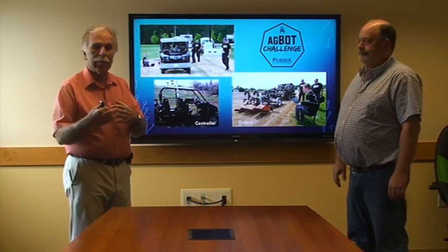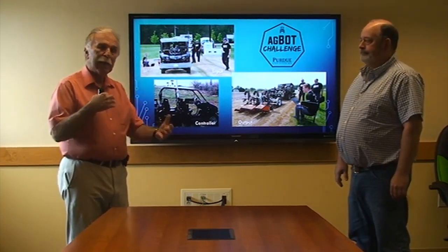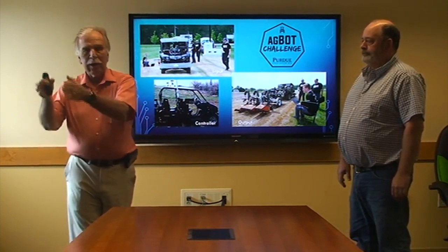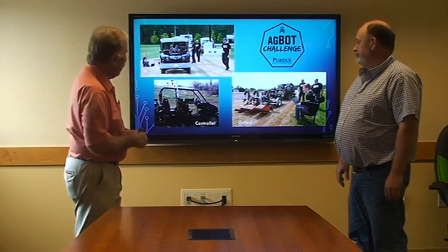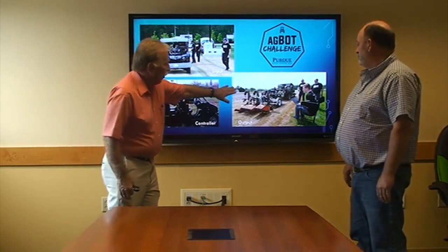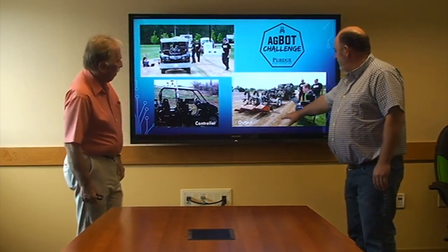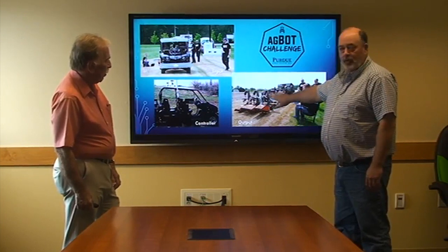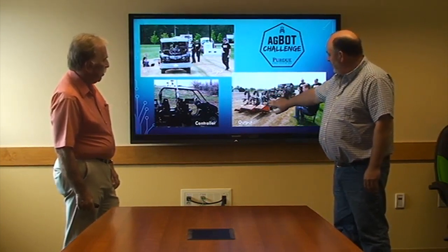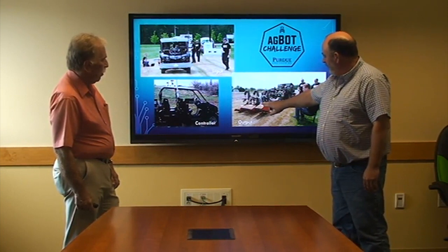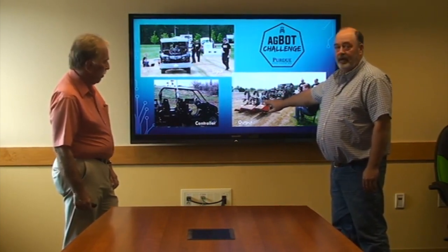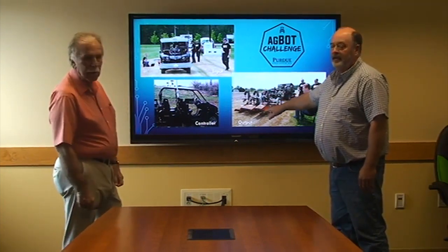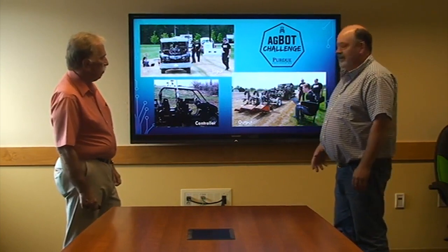So the camera that identifies the weed indicates the location of the weed, whether it is in the row or between the rows, etc. And then it feeds that back to our output device, which is basically a rototiller, these three orange things, and it has linear actuators that basically raise it up and down. And then within the row, we have some solenoids, which are basically on/off. That's another output device. We turn on and off this flow of liquid to spray on top of the crop, depending on what the weed is.